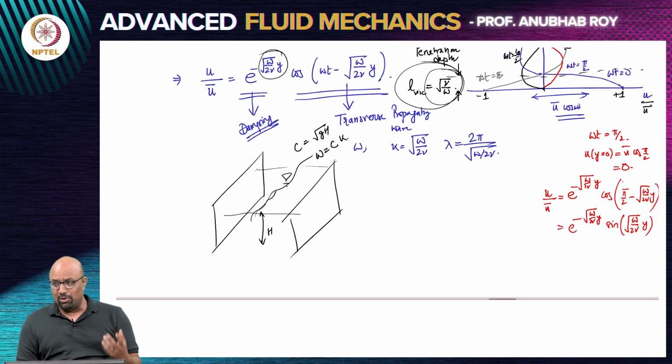Now, the waves could be due to gravity at the interface, or due to effects of gravity because of density variations. There are various mechanisms by which you can generate waves in a fluid. Now, if you have generated waves in a fluid and you want to find out the amount of dissipation that is happening, there is dissipation in the bulk, and there is dissipation at the boundaries.